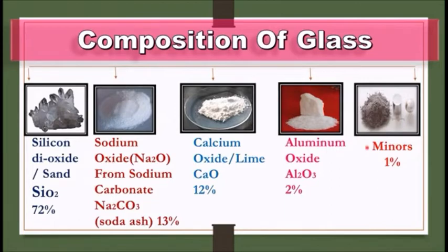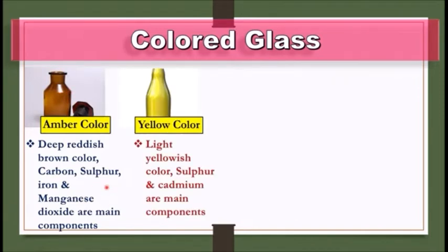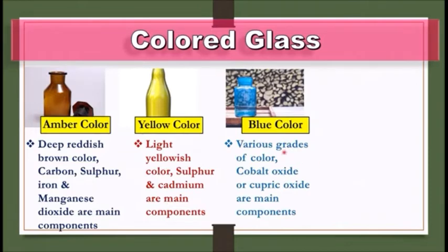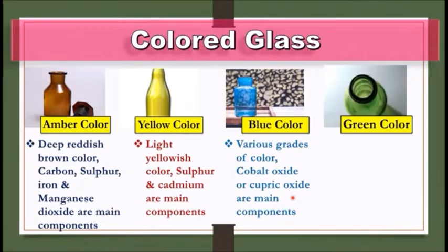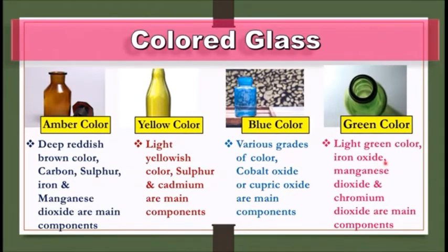So next we see the types of glasses. Type 1 is borosilicate glass. This borosilicate glass is more chemically resistant than other glasses. The second type of glass is treated soda lime glass. Type 3 glass is regular soda lime glass.